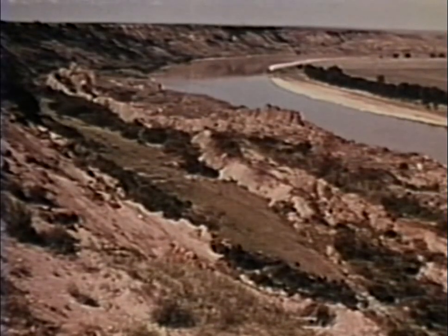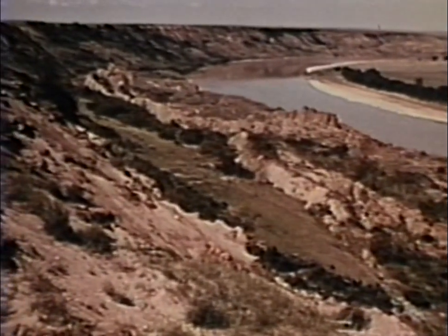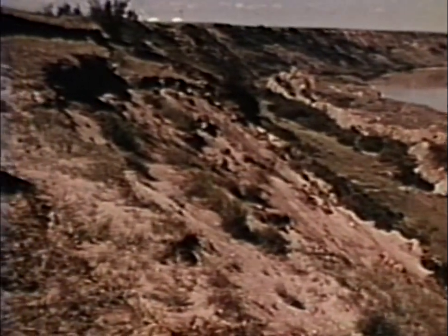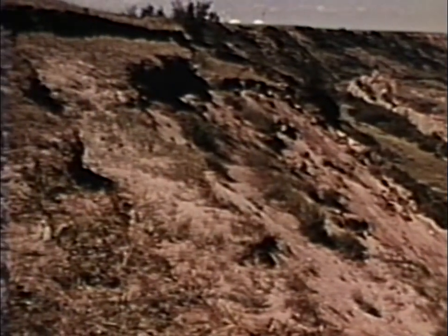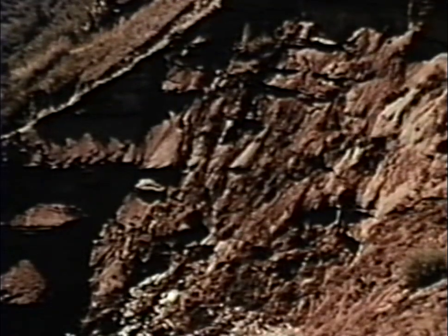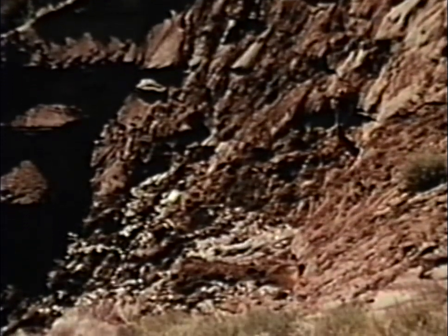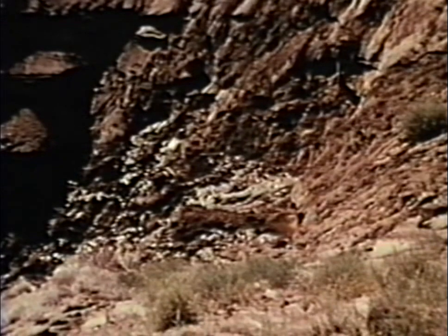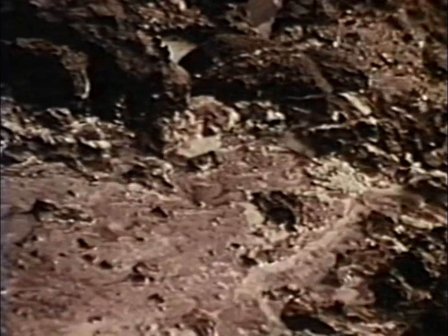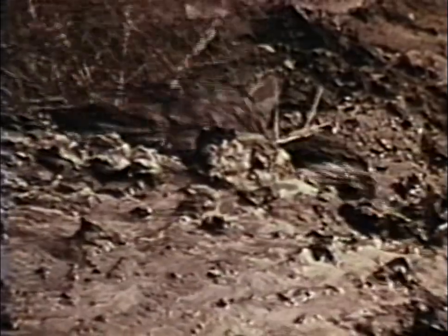At this riverbank location, groundwater has been continually a contributing cause of landslides or slumps. Year after year, the fallen debris is carried away by spring floods. The main zone of groundwater seepage is halfway down the slope. High groundwater pressure and the continual seepage from the bank cause earth movement that can develop into mud flows.